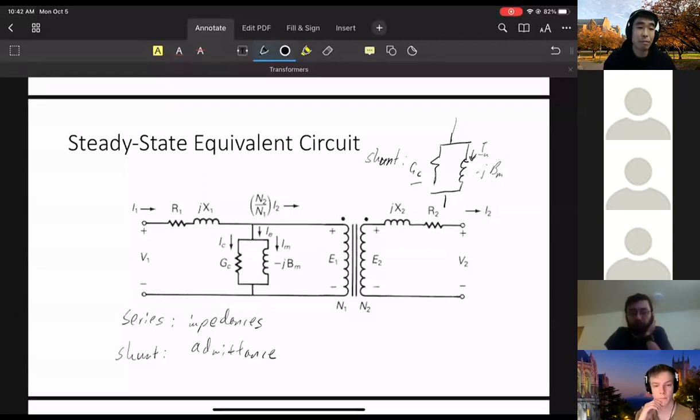But if we talk about shunt resistance, the shunt resistance is actually infinity, an open circuit. For the ideal transformer, I don't have the shunt, so it's an open circuit. That makes the language a little bit tricky. For the reason that I always want to say that when things are small, I recover my ideal model, this is a convention we have. It's very powerfully ingrained in our minds that small things should be close to the ideal model.